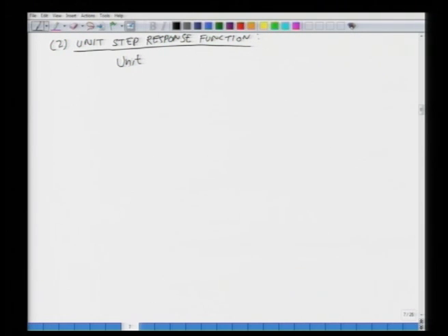Well, it is nothing but the response from what is called a unit step input. Okay. You have the unit step input which is being applied to your system, which is a catchment we are going to look at, and then this models that as a reservoir, and what you have is the unit step response function coming out of it, and this is denoted as G.